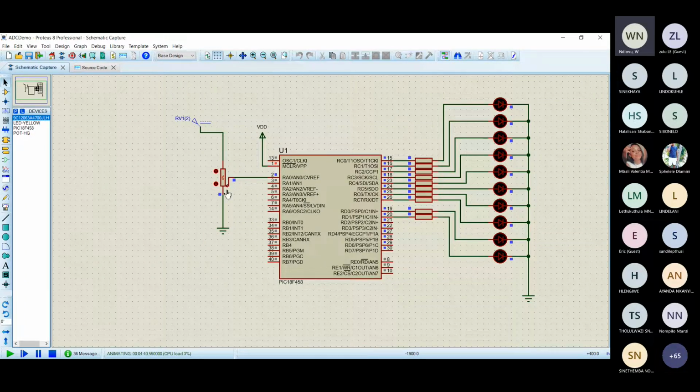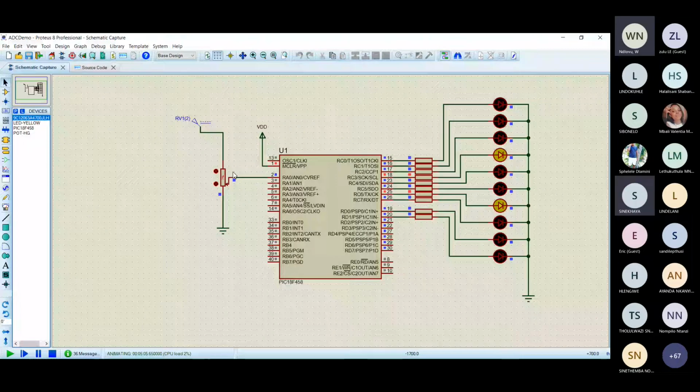Remember, if you look here, we've got 5 volts there, and ground here. So we've got current flowing in this voltage. And we said the potential difference is always between ground and the point. As I'm clicking this top dot here, I am increasing the resistance between this arm and the ground, but it's a small portion. When the resistance is small, this will produce a smaller number. When the resistance is maximum, that is equivalent to maximum voltage. So here we are actually converting resistance to voltage.